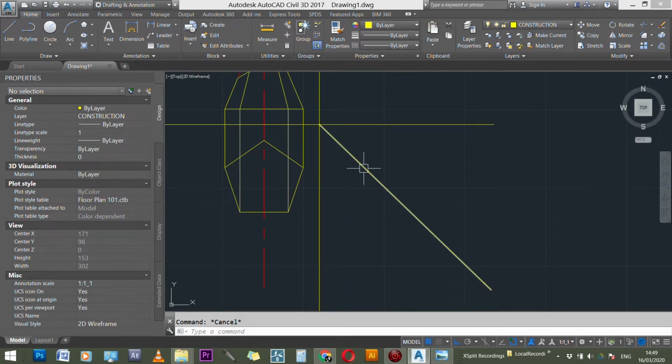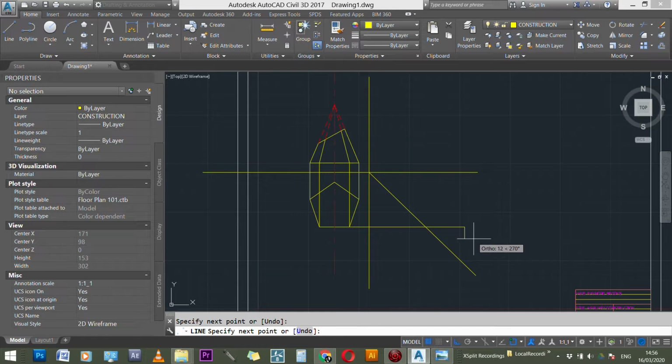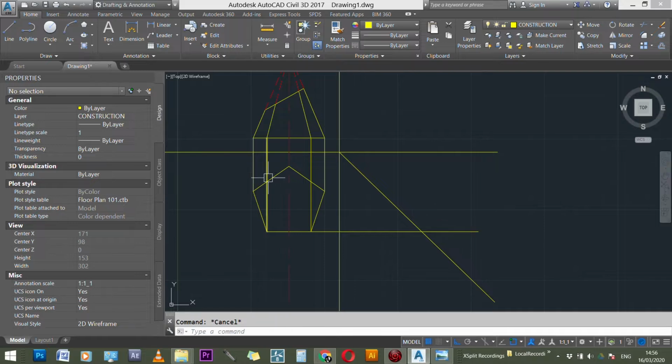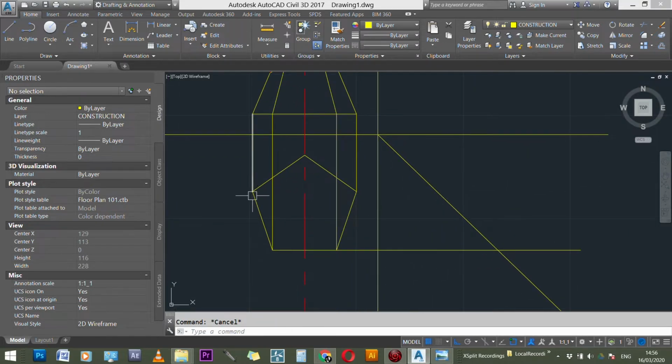Now what do we do at this point? At this point I'm going to project. Okay, so now that we have this information line, what are we going to do with it? I'm going to project all my lines from the plan, meaning from these points around the plan here, and I'm just going to project them through. It makes no sense projecting this point here because this point shares the same as the opposite point, similarly to this baseline.